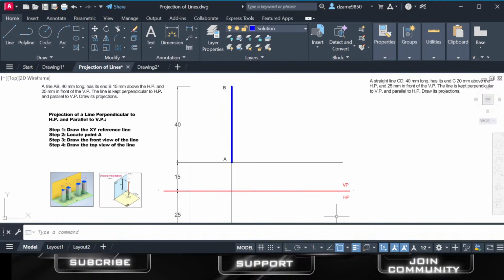Now, what's the purpose of layers? Let's just proceed again. Instead of you picking and sharpening a pencil every now and then, you simply select a layer. And before you select a layer, how is a layer created? By just clicking here on this icon of layer properties. The moment you click it, unfortunately it's not able to populate, you're not able to view it, but you're able to select and create different layers upon clicking this one. Once you are on AutoCAD, you'll be able to view that one.